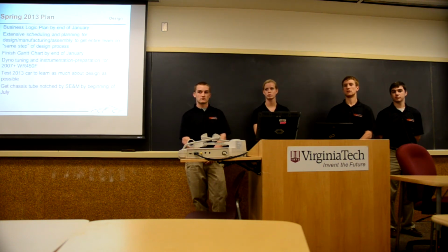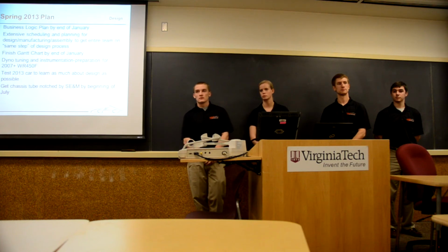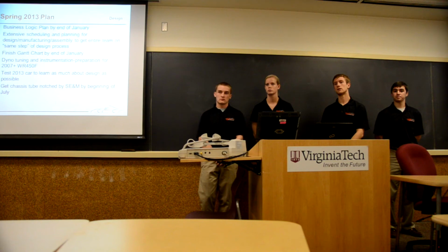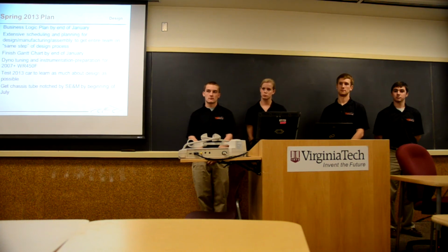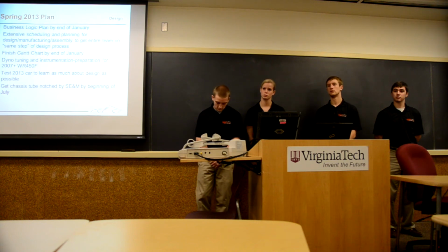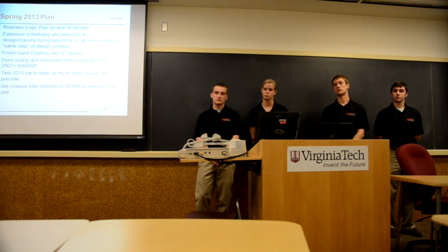I mean, not necessarily, but that's one thing that we've always struggled with in the past, is not modeling things, and one thing we pushed in '08 was modeling as much as we could and trying to design a race car. And you wouldn't believe how many problems we solved and how much time we saved by properly modeling things. We caught so many kinematic issues with the suspension by having a constrained model and playing around. It was a separate model, but it was playing around with where our max and min ranges were, and we hit so many things in the CAD that saved us from wasting money and manufacturing time. So I know that historically that's been a problem here, CAD modeling up front to a detail like bolt, nut, washer,